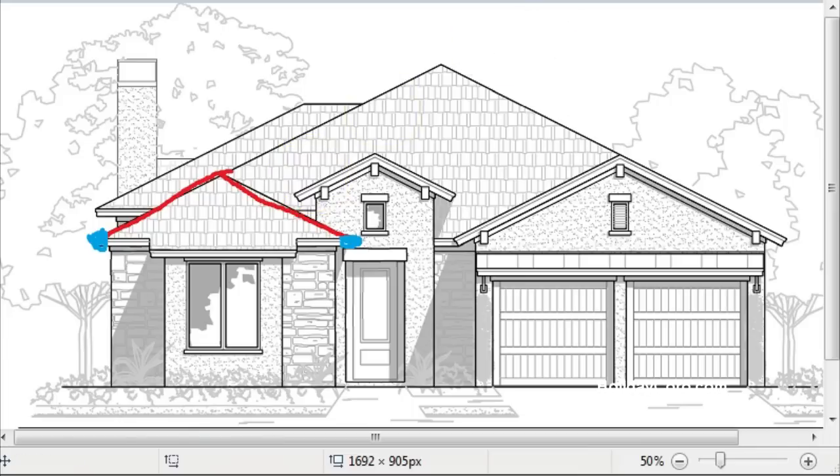So now we can control each half of this gable roof. Now, let's go ahead and do the remainder. For example, we may wish to control this section over the front door as one total section, so we'll just run one entire length. Again, assuming that there are no power limits, we'll put a controller here. Where you put your controllers, you'll need to be thinking about that, because when you're finished, you're going to need to wire signal and power to each one of these controllers.